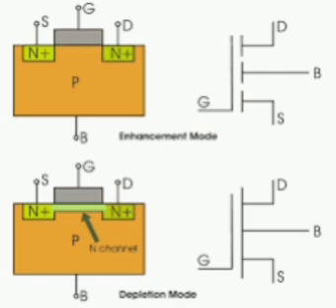Conversion efficiency of a solar cell is the ratio of electrical output power and incident optical power. Fill factor of a solar cell FF equals VmIm by VOC times ISC. Practically fill factor is approximately 0.7 and maximum efficiency is 25%.